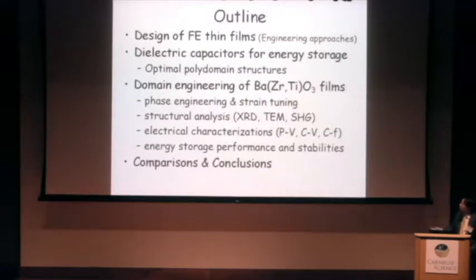Then I'll give you the experiment data: structural analysis by XRD, TEM, second harmonic generation, and also electrical characterization results, PV, CV, and CF. From the PV, you can get the energy storage density and also the efficiency. As a conclusion, I'll compare the performance of my BZT thin film capacitors with some of the top performers in the field.